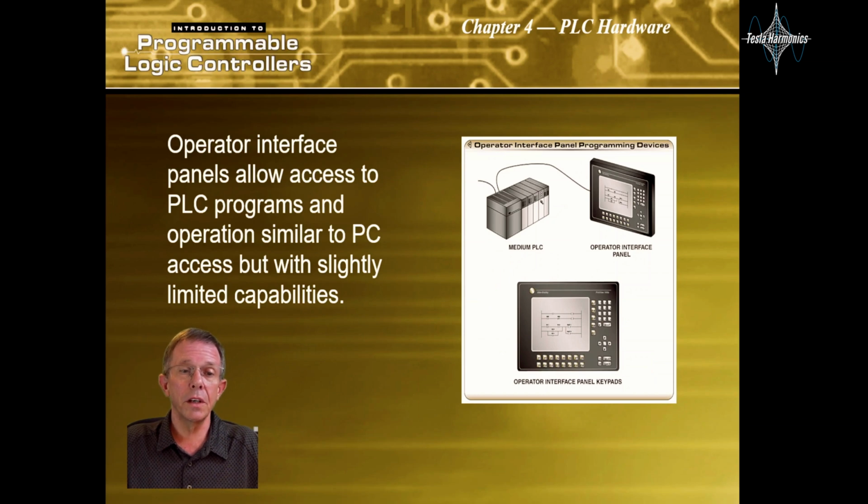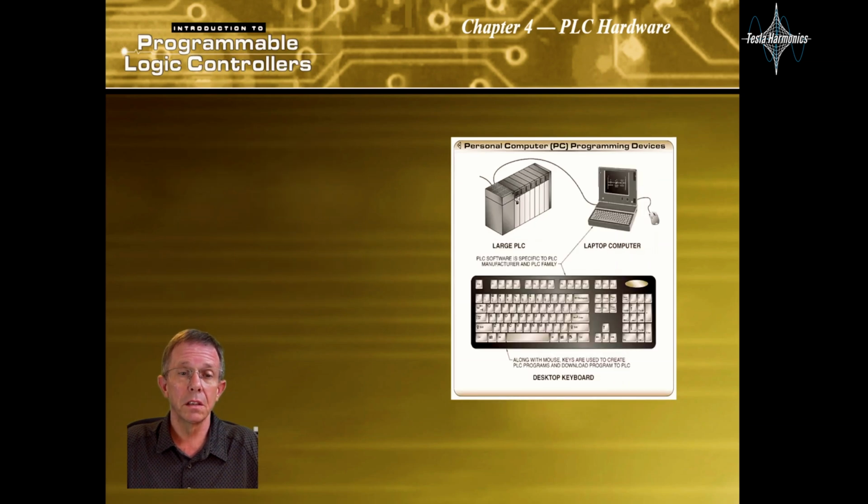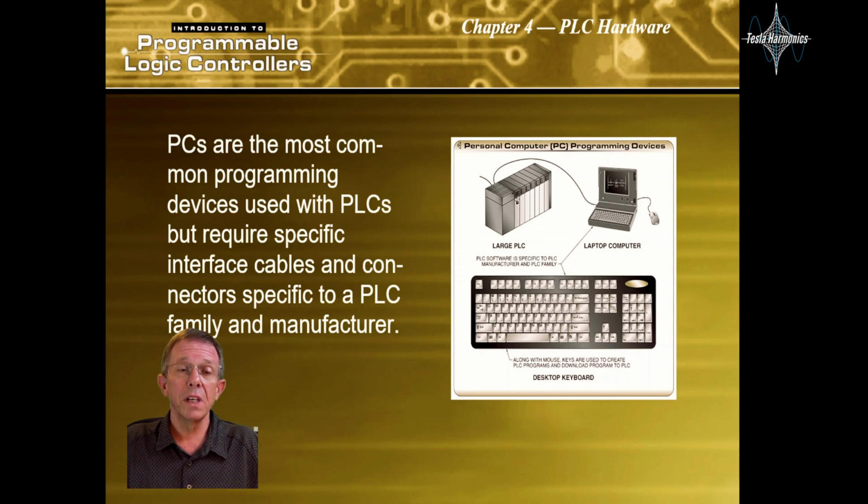Operator interface panels allow access to PLC programs and operations similar to PC access but with slightly limited capabilities. PCs are the most common programming devices used with PLCs but require specific interface cables and connectors specific to a PLC family and manufacturer.